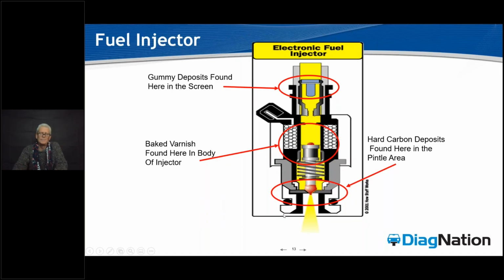And what's going to happen there is we're going to start to just get more heat and wear and resistance on that injector solenoid. When we want to think about how an injector winding burns out, this is the process that begins to get it there if we take normal wear into consideration and we're not looking at an open circuit winding failure, okay? But even sometimes when we are looking at an open circuit winding failure, that's the beginning of the cause, because it's been working on it for so long and everybody's like, oh, you don't have to clean these systems anymore. Yeah, no, you really do.